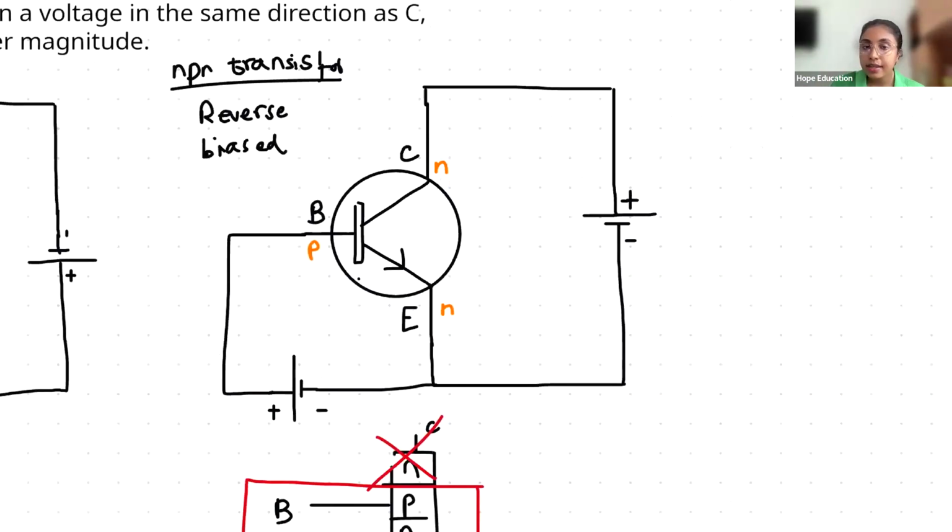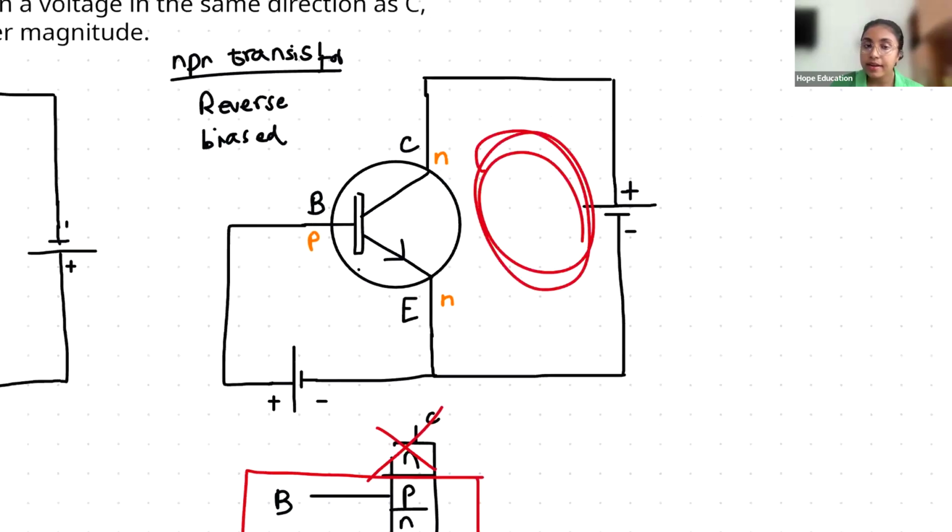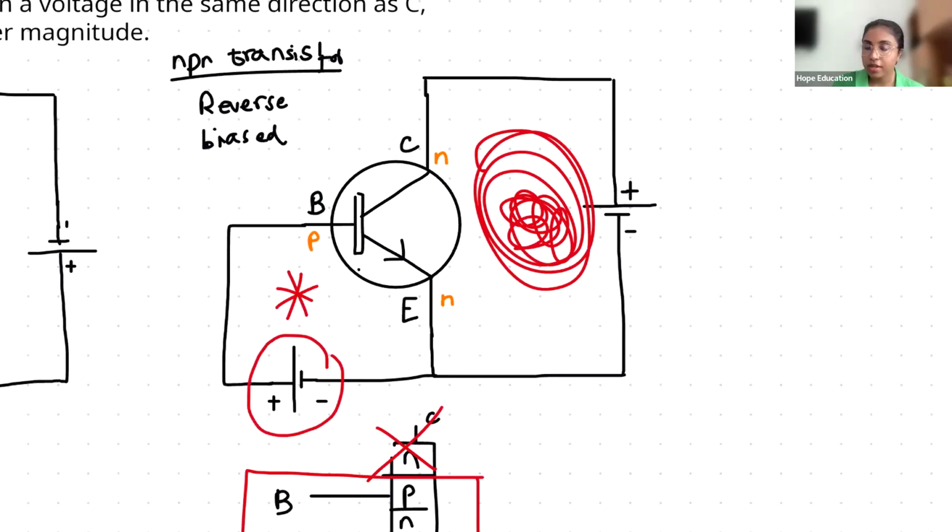So kids, in this biasing circuit, the current depends on this. You just have to give 0.7 volts to this. Here only a tiny voltage like 0.7 volts is given. A larger voltage is automatically created here. Let's say I refresh this again, listen carefully. Give a tiny voltage like 0.7 volts here. That tiny voltage produces a tiny current. That current creates a large current in the big circuit. To match that large current, we apply a large voltage here. Right? Did you get it?